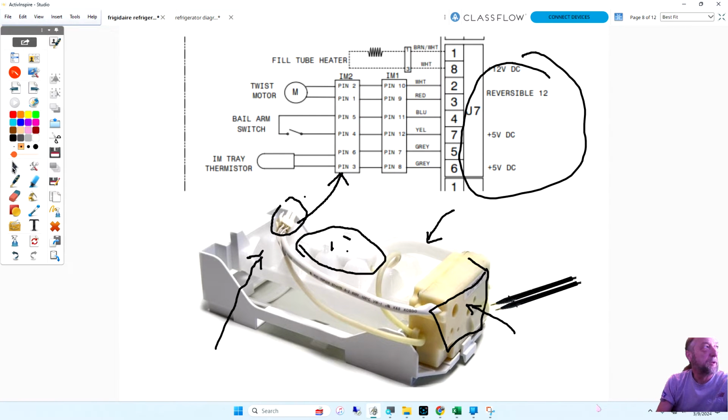I'm just going to use 2 black meter leads because I only copied one by mistake. So I would go into the plug here and here, which would be pin 1 and 2. So basically, you're going right inside this plug here. But we want to leave it connected, so we're going to go on the back side with our skinnier leads. And what are you going to do? You're going to do what in order to make this test, and what are we looking for?